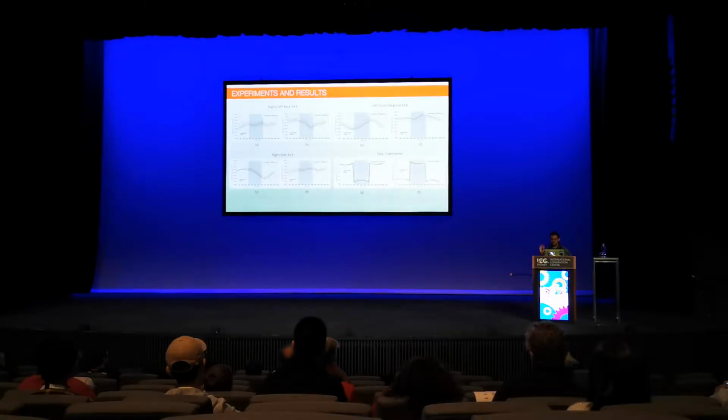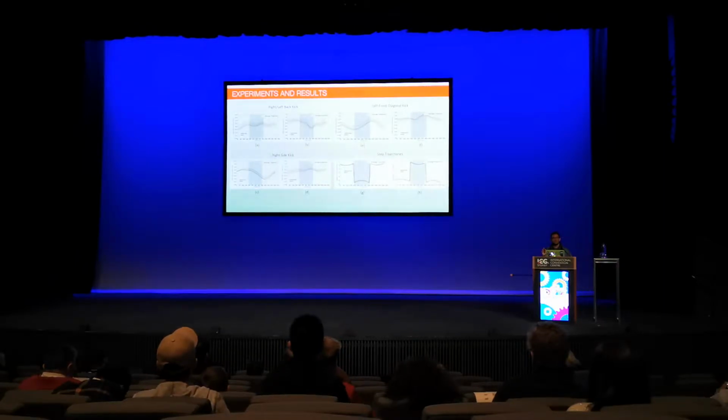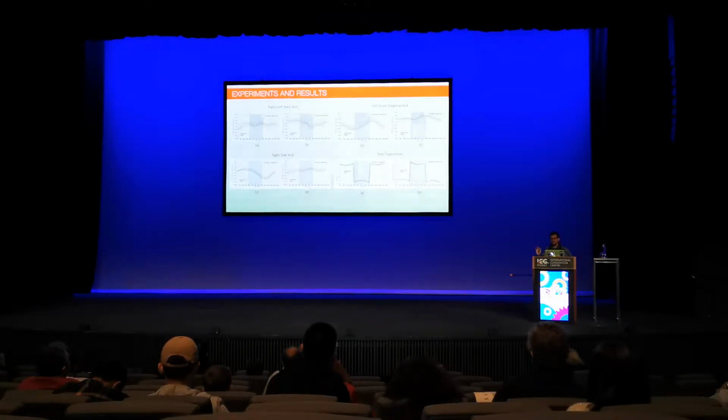An important question that is raised is where the robot becomes unstable with all these shifts of center of mass. As can be verified in these graphs, the center of mass for the 300 kicks was bounded between negative 2.0 to 2 centimeters, while the supporting foot trajectories in figures G and H were bounded by negative 6 to 6 centimeters, which shows that the center of mass was always in the support polygon of the robot. This verifies why the likelihood of the robot falling with walk kicking is less than 1%, and actually you can use these graphs to then create controllers that can control the trajectories of center of mass and actually generate kicks while walking.